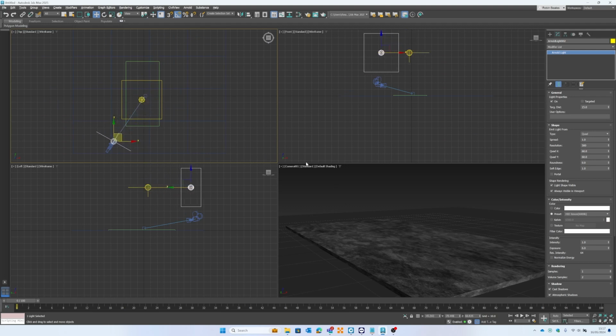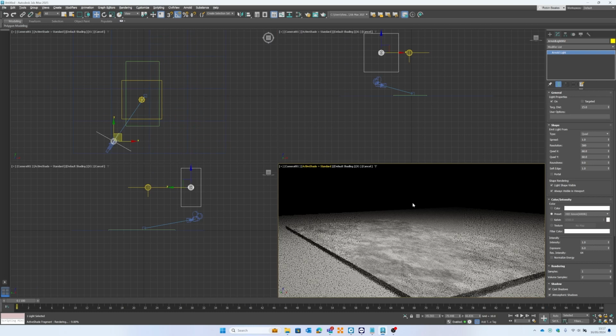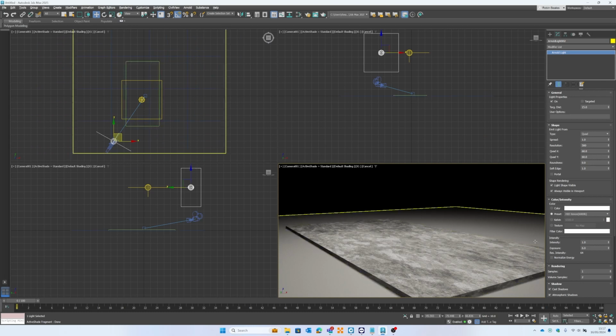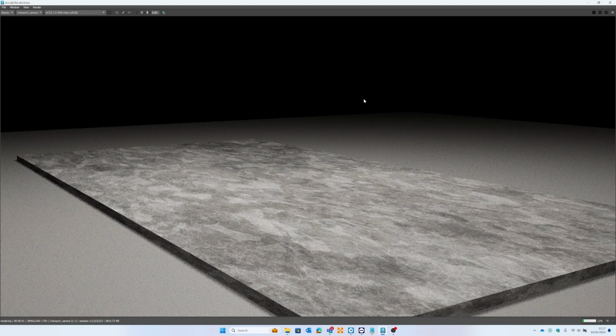So I'm going to have it facing my model, and I'm going to place it behind the camera lens. Again, remember to turn on your active shade if you've got the ability to do so using the spec of your laptop. You'll be able to see how that's changing things. I'm now lighting up this area, so I've got no shadows in this area, and my shadows are all going to be on the back of my component here. Again, I'm now fairly confident that if I go and hit render, the front of our model is going to be much brighter, and we can see the texture coming through already on the front down here and down here.